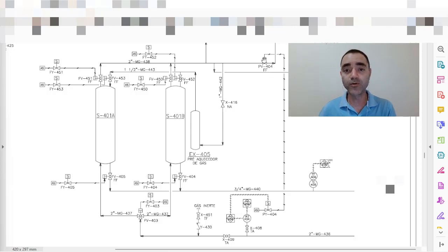So if I have a compressor, for instance, or any other process that relies on the pressure that comes from this control valve, I must make sure that this control valve has a pressure drop that fits the design condition, but also fits the turndown conditions. So I need to know what the variation in the pressure drop is when I am at 100% of capacity, and also when I am at 50% of the capacity, 75% of the capacity, and so on.